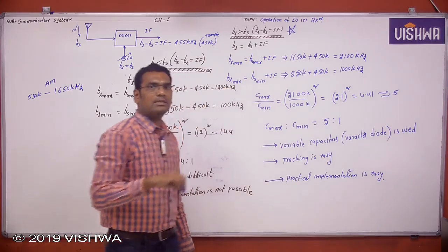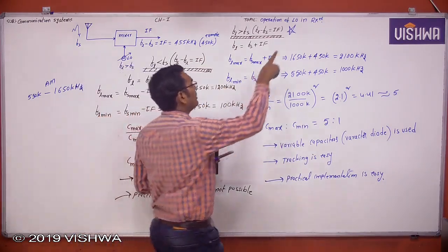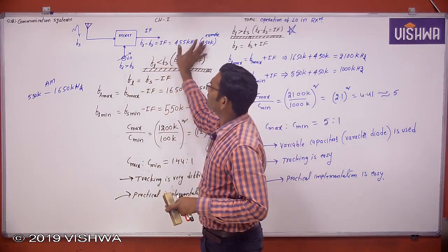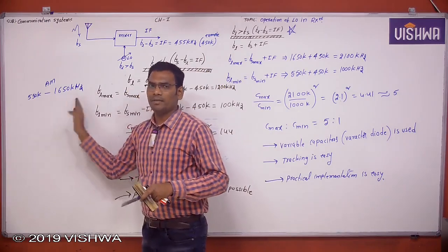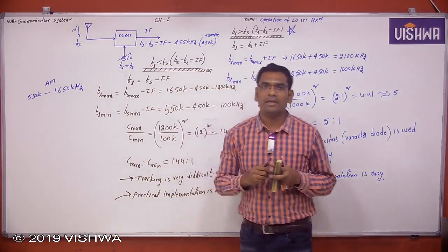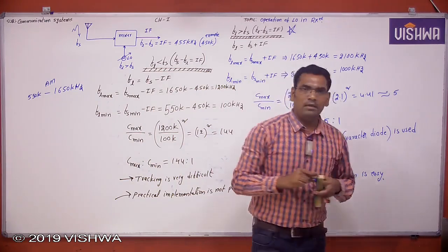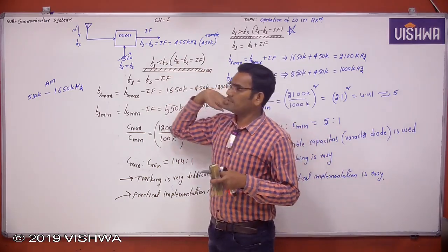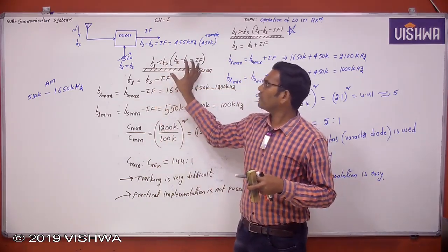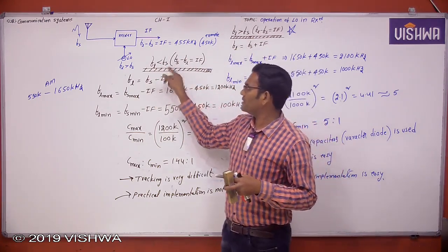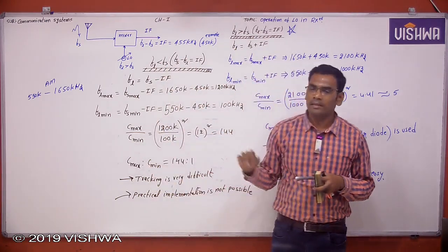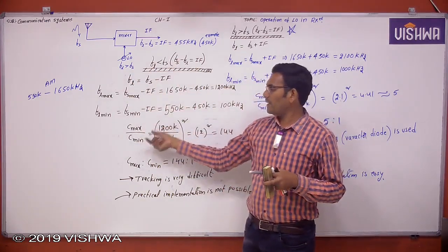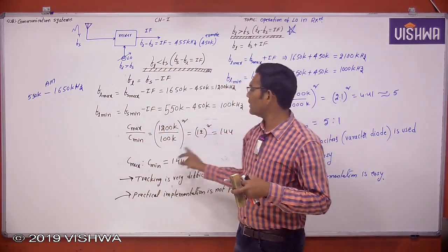Okay, so this is the operation of the local oscillator in the receiver. This local oscillator is adjusted to maintain IF constant to cover AM range or FM range, whatever it may be. It may be in AM receivers or FM receivers. This is how the local oscillator frequency is operated in the receivers. Why Fl greater than Fs is preferable, and why Fl less than Fs is not preferable, this is the reason. Sometimes the question is asked, how many capacitors for this much frequency, or what maximum to minimum capacitance ratio is used, and this formula is also useful to you.